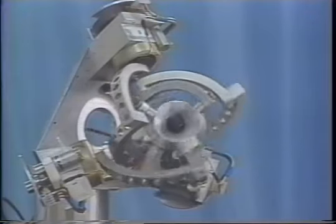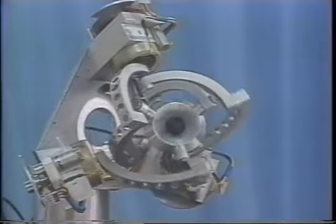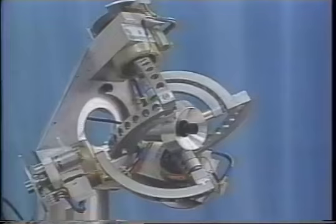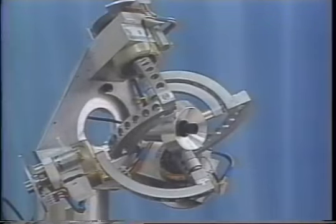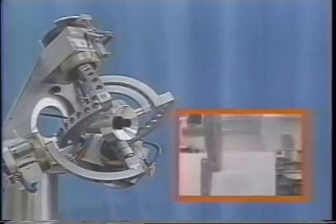An example trajectory is now shown in slow motion and at full speed. A dynamic model of the mechanism has been developed and implemented in the controller, which is based on a high-speed DSP. The dynamic model can be computed in real time at a servo rate of 500 Hz.